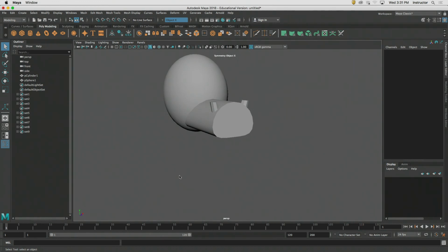I'm about 2% done on the block out of my model. There's a lot of information in here that I want to try to capture, okay? We don't want to be relying on the sub-D algorithm or maybe even Mudbox to help us figure out and craft what that final result is going to be. So we need to be good modelers. Keep using this box modeling technique of starting with something simple, slicing and extruding and moving, scaling and rotating the vertex, edges and polygons where they need to go. It's a pretty fun system.